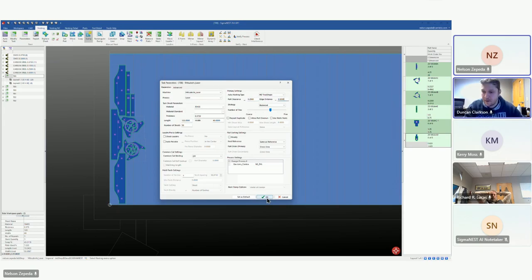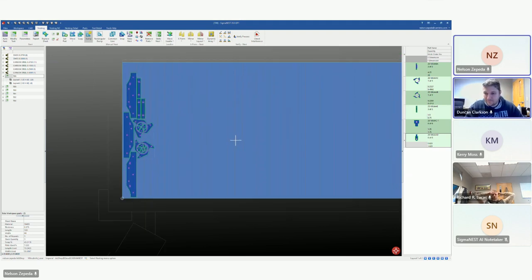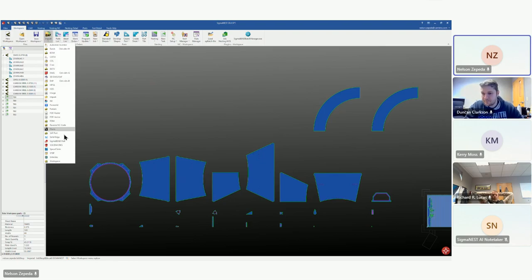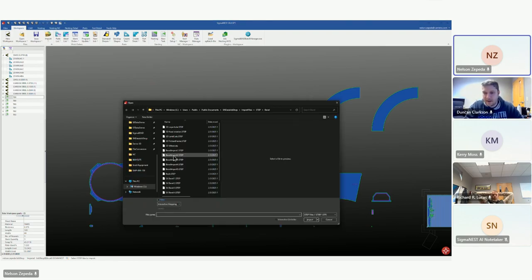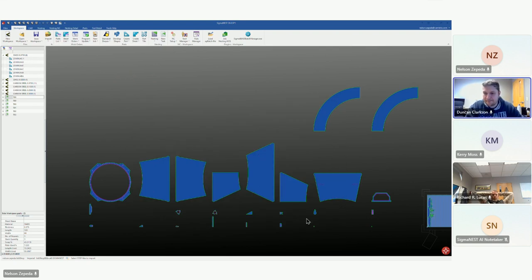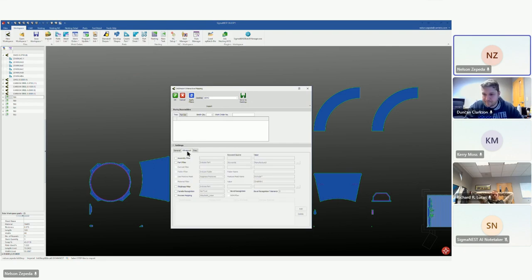Great. Okay. And this can handle beveling? Yes. So for beveling, there isn't anything special in terms of nesting you have to do. Let me see if I have a bevel part here. I should have some. Yeah, I don't think I sent anything that was beveled, so apologize for that. That's perfectly fine. And I'm just going to use step files, but for bevel parts, the only thing you have to do is just turn on this checkbox, and that's really all there is to it.